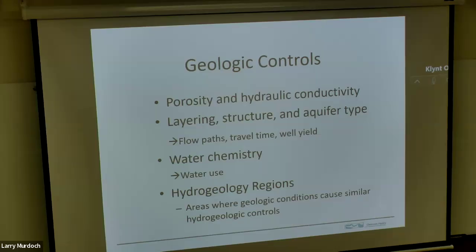The geology is going to control the materials that the aquifer is formed from, the minerals, and the interaction between the water and the minerals will be an important control on the chemistry of the water. And the chemistry is going to play an important role in how the water can be used. If there's really high dissolved solids, salts in the water, too salty to drink, then you can't use it for drinking water. And if it's fairly salty, it might be too salty really to do anything with. You can't use it for agriculture if it's got too much salt in it.